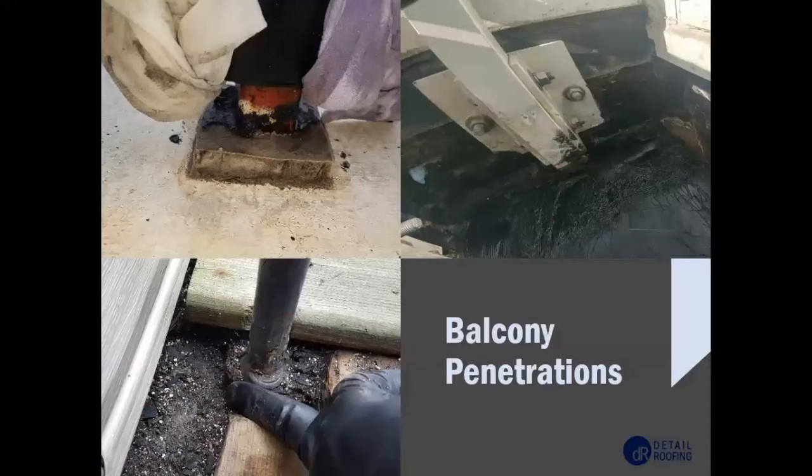Penetrations. Again, very commonly, as well as the upper roof surfaces, any exposed penetrations or penetrations that have deteriorated sealant on them do need to be looked at and addressed so that they don't cause potential leak issues on balconies, especially because you have the penetrations from the railings, not only going into the field membrane, but into the side as well with the bolt penetrations.